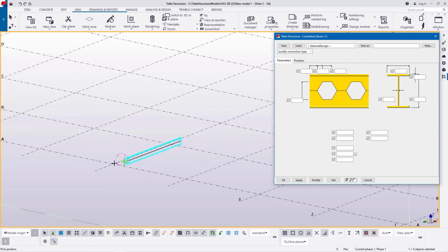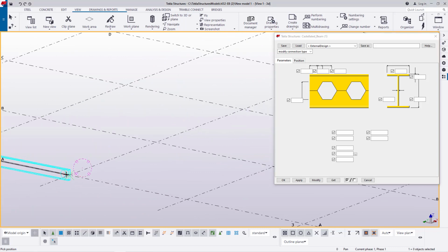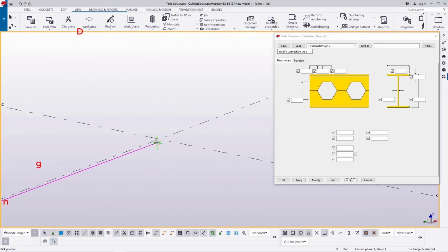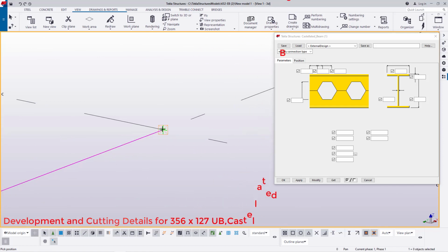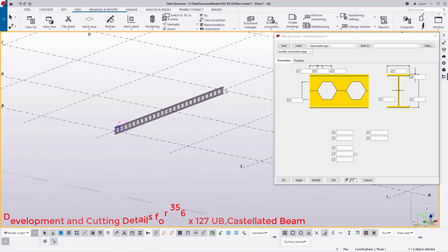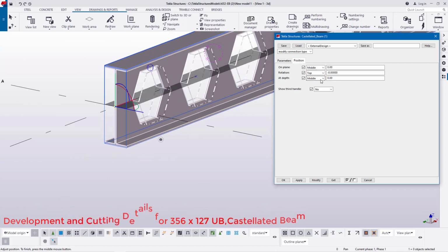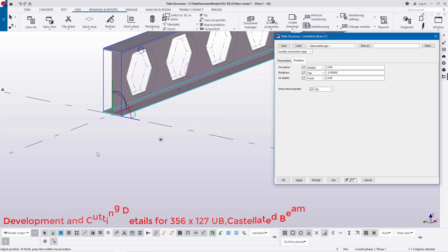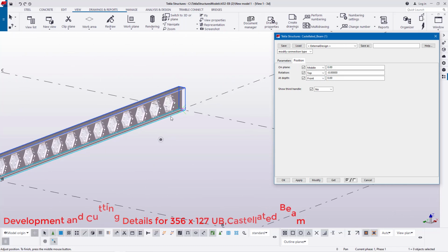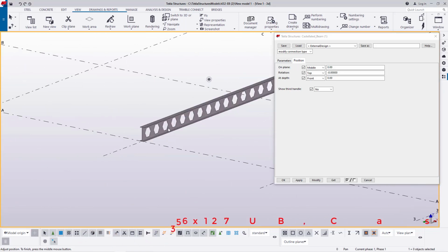And what I'll do is define the length from one point to the other, stretching to a length of 12 meters. Let me terminate it somewhere here. Then give it some time to process the information, and here we are, and it is exactly on the same position. Let me double click on it once again, come to position and lift it up slightly on top of the grid line. So there it is, and if we zoom out, you'll see it's actually on the grid line. Previously it was halfway up, halfway down.